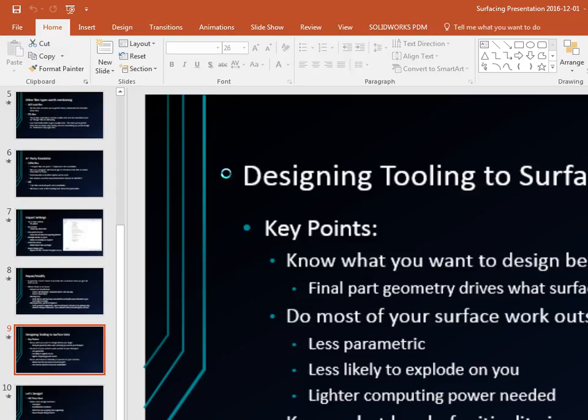Features, curves, split line. So I'm going to split. We're going to do a silhouette of plane 1, the plane that is my draw plane of these faces, and it's going to split the face where it's tangent to the normal. You can see, whoa, that's messed up. Maybe I should have tested this first. Okay, well, I'm going to delete that stuff anyway, I think.